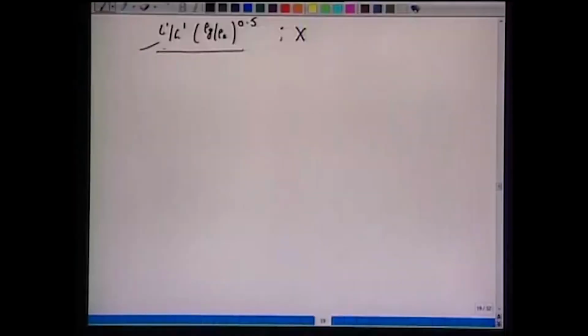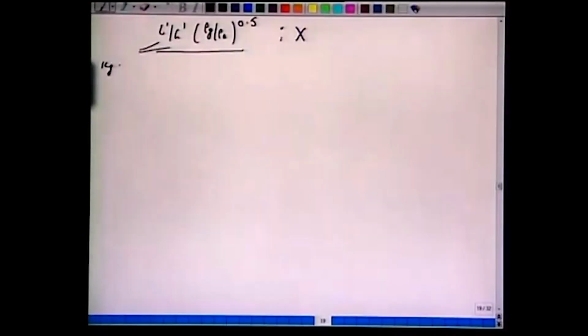Now L bar and G bar are in kg per second per meter square, where the meter square is the cross sectional area; that is what we are supposed to find out. So, that we get the area, and from there we get the diameter of this column. The flue gas composition is given here. Let us calculate now G in kilomole per second.